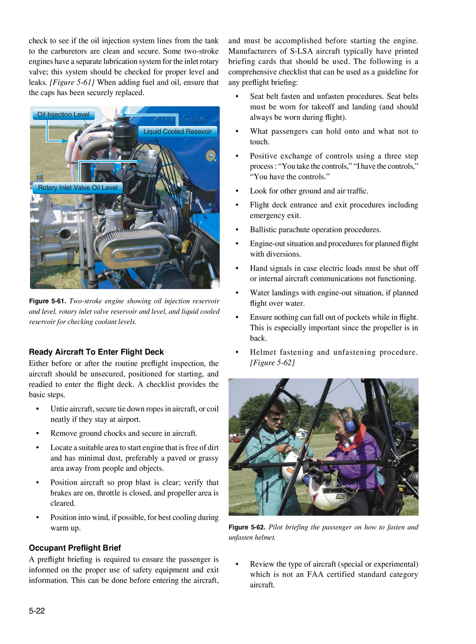Locate a suitable area to start engine that is free of dirt and has minimal dust, preferably a paved or grassy area away from people and objects. Position aircraft so prop blast is clear, verify that brakes are on, throttle is closed, and propeller area is cleared. Position into wind, if possible, for best cooling during warm-up.